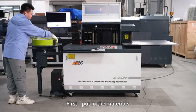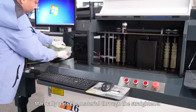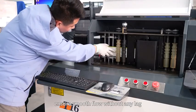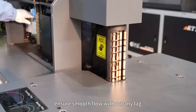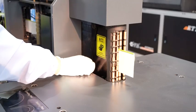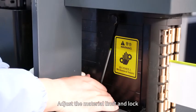First, put in the materials. Manually pass the material through the straightener until it reaches the bending outlet. Ensure smooth flow without any lag. Adjust the material limit and lock.